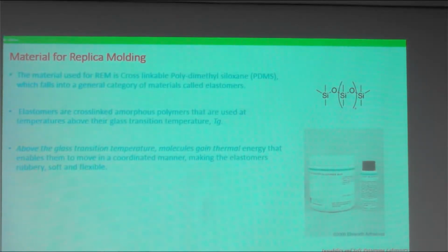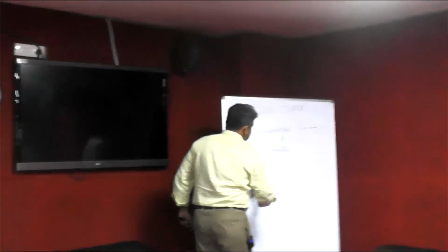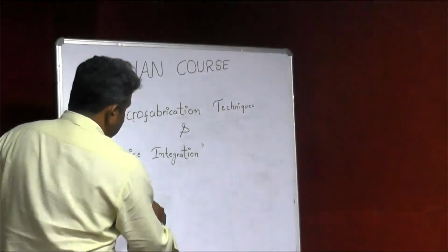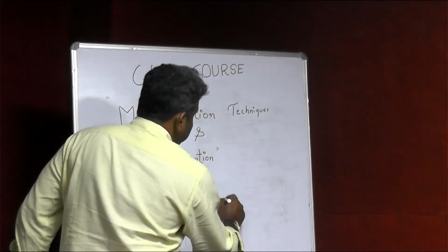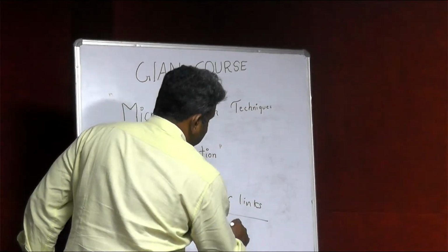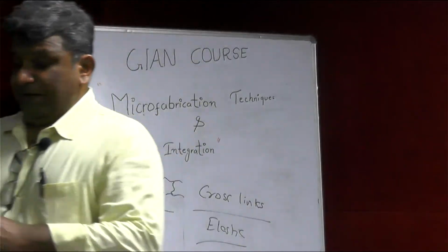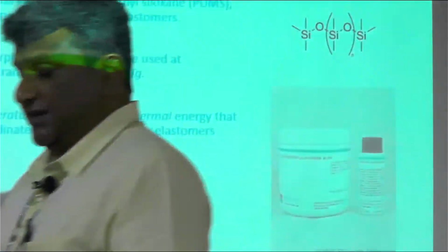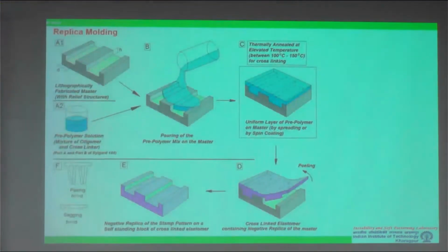It's something like this. You start off with these individual chains, and when you thermally anneal, they form these crosslinks, physical crosslinks, which give them the elastic nature, right? And how does it happen? It happens when you thermally anneal this thing. This is important for the subsequent discussion that is coming up. That's why I spent so much time and emphasized on this.